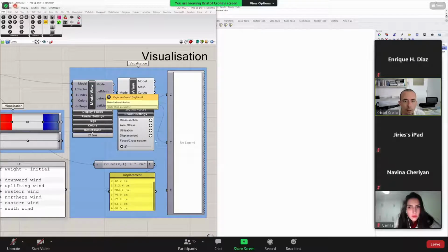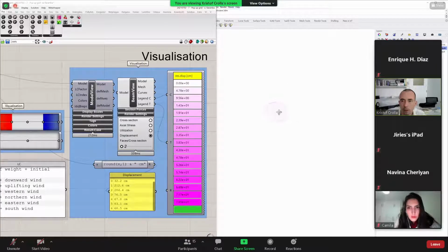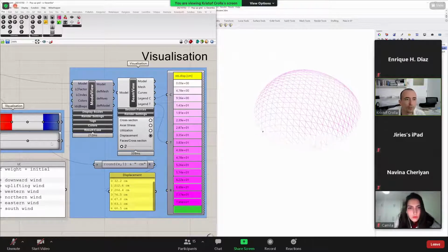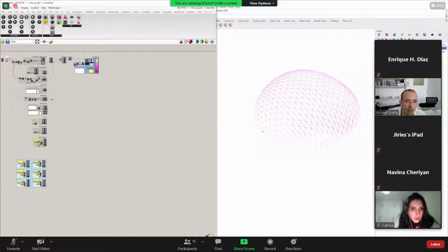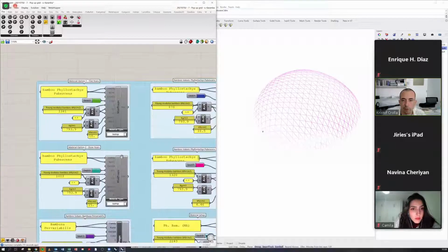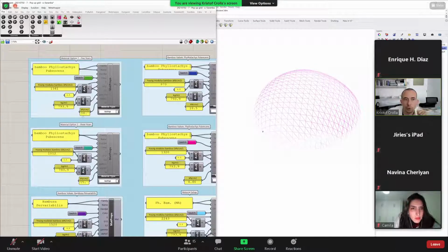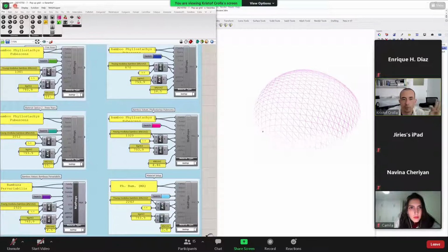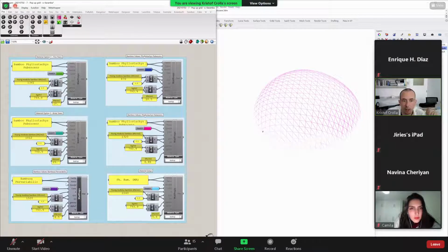One last thing that we added here, in the bottom file, you'll see some different material values for different bamboo species, like 5 years old, 3 years old. We've looked into the literature and found a few different values for the same bamboo species, or even different bamboo species that you may want to have. If you want to work with local species, you just need the elasticity modulus, the Young's modulus, and the yield strength of your bamboo. And then with that, in principle, you should be able to pop it up.